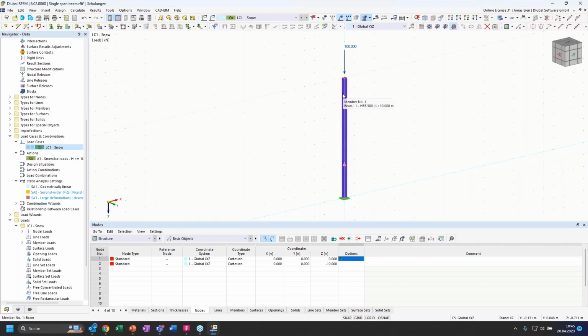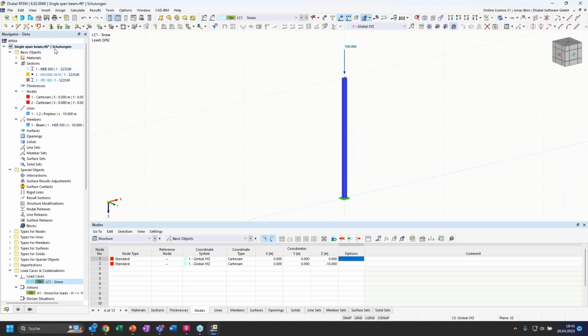This is a structure that has been investigated for stability for a long time. So I think Leonhard Euler already in the 18th century provided a solution to address stability of such fixed end beams or fixed columns under pure compressional load analytically. But this means we can also check the results that we obtain with RFEM very easily and check if the results hold against the analytic solution. So yeah, this is also known as Euler case number 1.